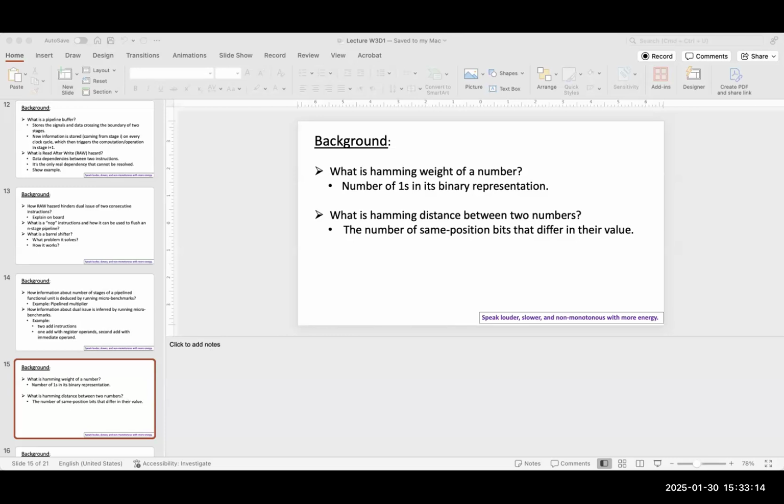So the question was how can we infer this information by performing CPI indexing of different instruction benchmarks? CPI indexing is where you run a benchmark, record it, run it multiple times, and then average how many cycles are consumed per instruction to execute that benchmark.